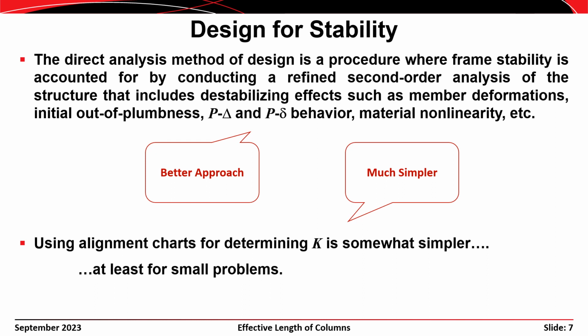Even though the effective length factors are a bit dated and are included in an appendix to the specification instead of in the main body of the specification itself, they are still useful and provide a measure of the amount of restraint provided at the ends of columns, even if some engineers would argue that it's an imperfect measure. So we're going to introduce effective length factors now and then revisit the details of the other approaches later.